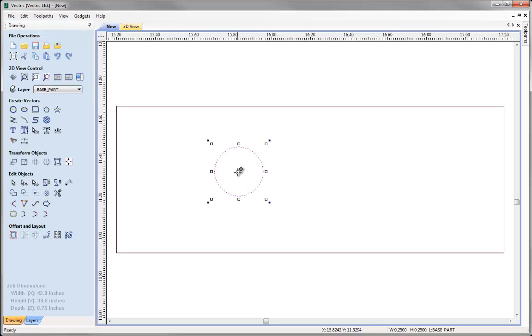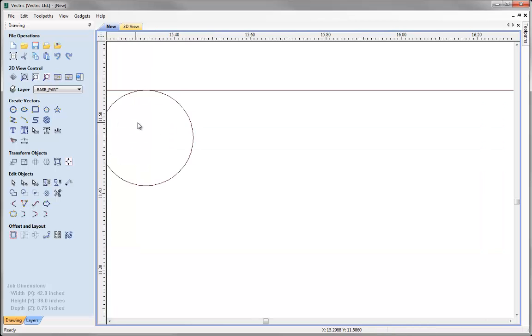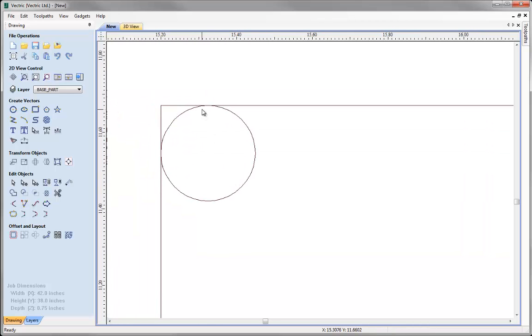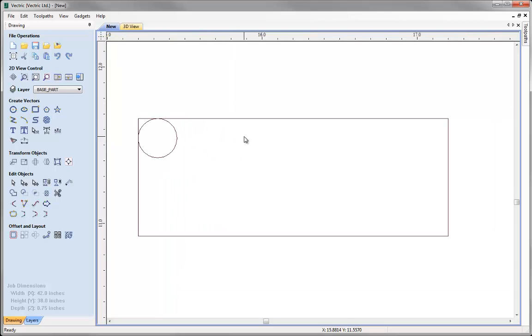and I'm going to imagine that I'm the tool and I'm coming up to the corner, and I've drilled up as far as I can into the corner without overcutting. Now, as we can see, we are going to be left with an internal radius, obviously where the tool couldn't actually get further into the corner. This is going to cause problems for when the tenons come to slot into these mortise slots, as they're not going to be able to get in because of this excess material left in the corner.